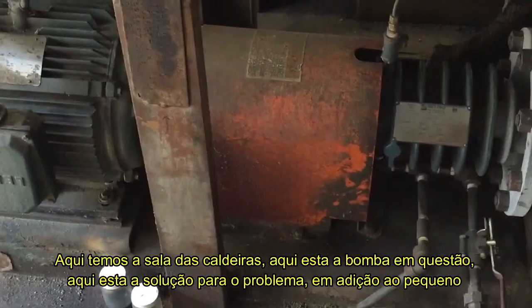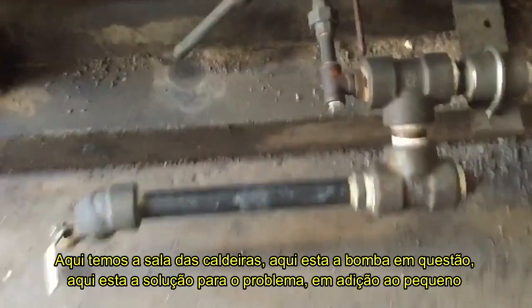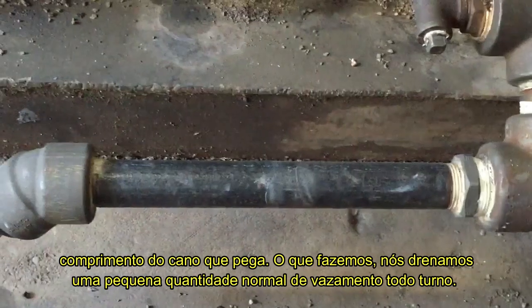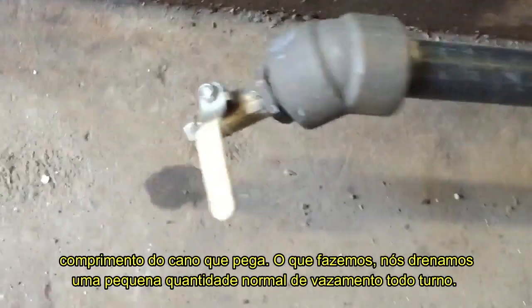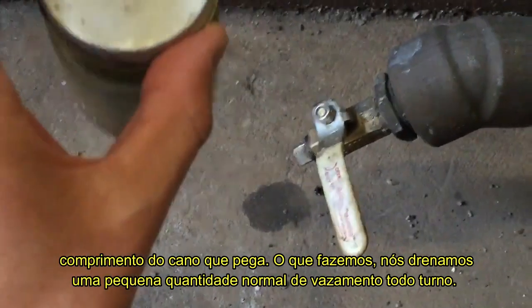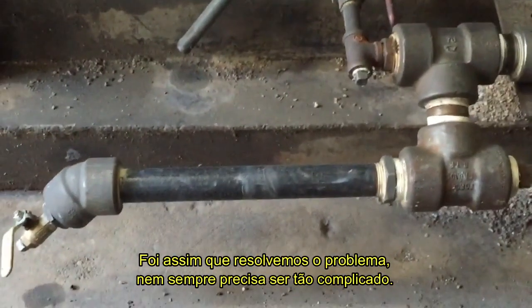Alright, here we are in the boiler room. Here is the pump in question. Here is the solution to the problem. An addition of a very small length of pipe to catch normal leakage from the seal that's allowed. Out of this valve, we drain a small amount of normal leakage out every shift. That's how we solve the problem. Sometimes it doesn't always have to be that complicated.